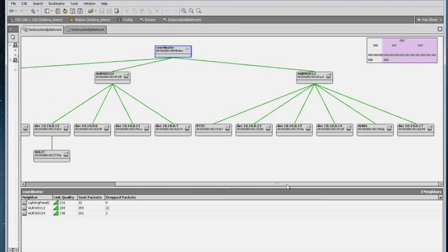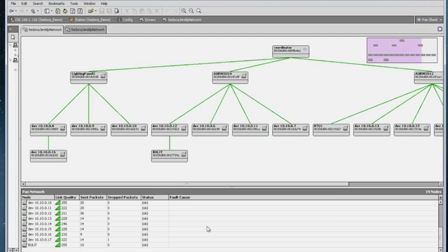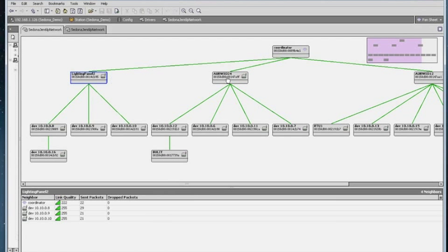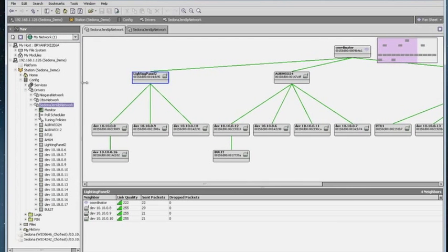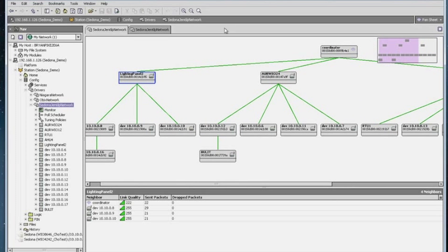So again, this is how you can manage the network, but you can see at a glance by selecting the coordinator very strong links. If you simply place your mouse in the white area of the screen, you will get all of the connections between the devices, and nothing's yellow. You can go from each one to look at the different connections between devices and verify what's going on. Now you have NA here. Now that's very important. That means that the pan info polling was missed. So you simply go back into your pan sheet or property sheet, delete and reload the pan info. But again, this is how you can manage your network more effectively to troubleshoot if you're having issues. So in a controlled network, this is a very valuable tool, especially when you get up to 100 or so devices on a network, as we've done before, being able to identify where your weak links are, if any.